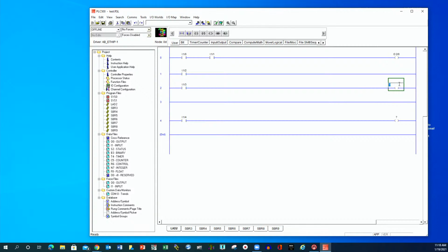This thing will let you put a 0 instead of an O and a 1 instead of an I, but it will not run it. So when you go ready to, it's not going to throw an error up like a normal PLC would, because normally it would say, nope, this isn't a valid word. If I was to put a 0 here instead of an O, it would accept it, but it would not run it in the simulator. It just wouldn't turn on. It wouldn't know who to talk to. So at least that part works nicely.